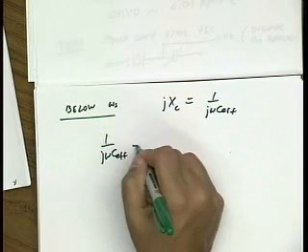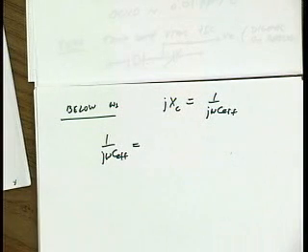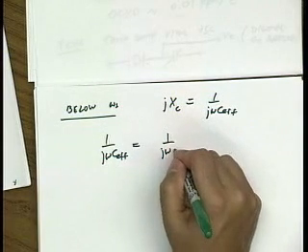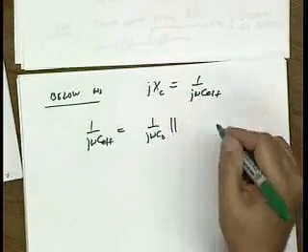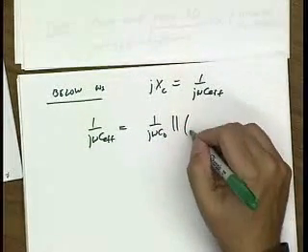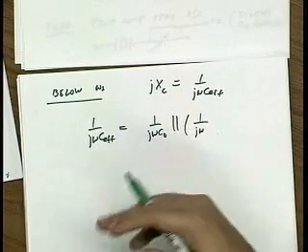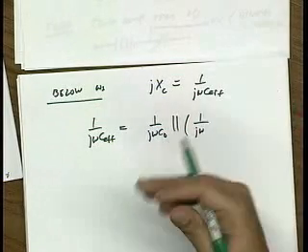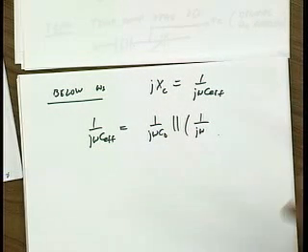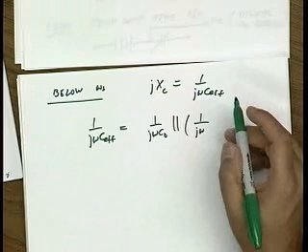Well, all we do is set the value of capacitance equal to the equivalent circuit value. Let's assume the fundamental mode is all we are concerned with here. And we can do that because at the first resonance, let's say the next mode is at 3 times the frequency, those reactances have negligible loading.